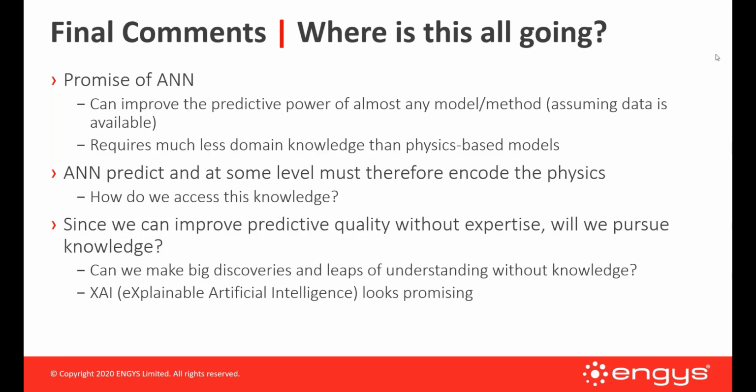It needs to be 1,000 geometry variations around a theme, and they need to be representative of what you anticipate will be changed by the designer. It doesn't have to be exact. Our experience so far indicates that as long as you're training in the general region, it'll figure out what to do, but you need a lot of cases basically.